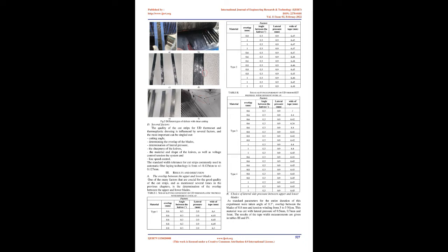The prepreg was shear cut in the longitudinal direction by two rotating circular knives, Fig 3. The lower knife has a cylindrical shape and carries the prepreg during the cutting process. The upper knife has a dish-like shape. The two knives have a minimum overlap distance to avoid damage while rotating 12. Overlap distance and knife diameters determine the cutting angle, Figs 3 and 4. Continuous but elastic contact between the knives was realized with a compressive spring mounted on the upper knife axis.